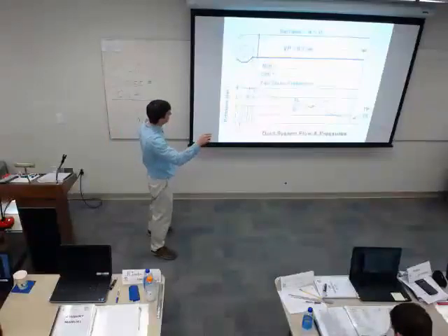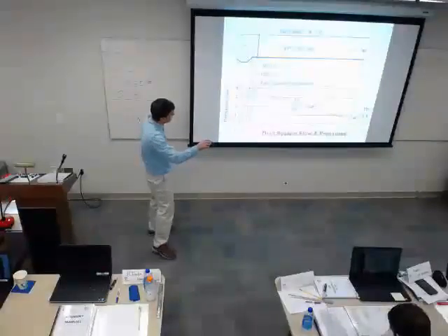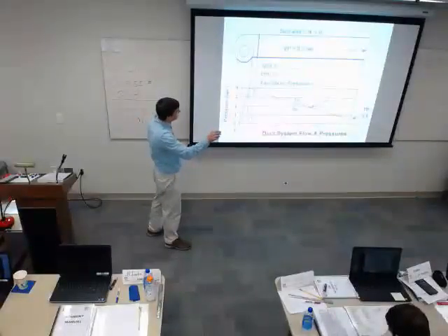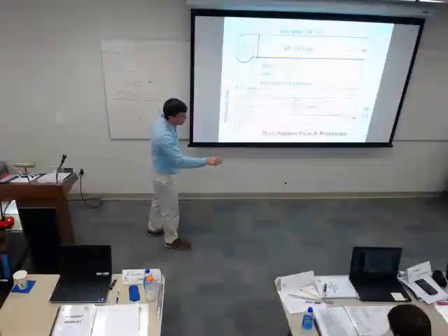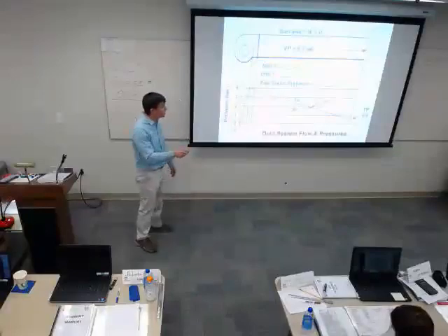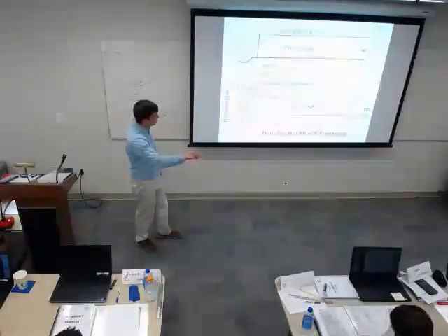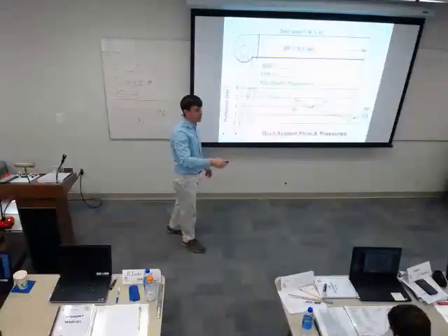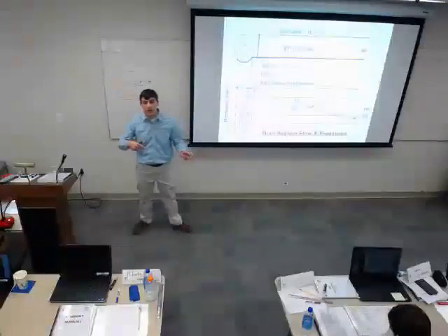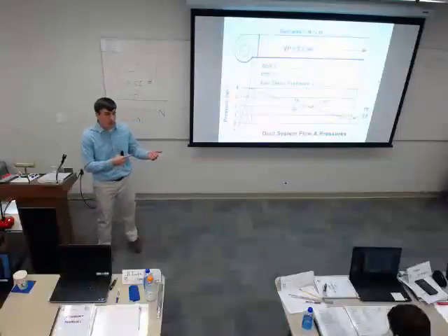And the point of this really being that I'm going to lose pressure as I go. So friction is going to cause me to lose potential energy as I go down the duct until I get all the way out of the duct. Now notice the velocity pressure stays the same. There's no change in size here. So what goes into the box must come out of the box. The same airflow rate is going through the box.